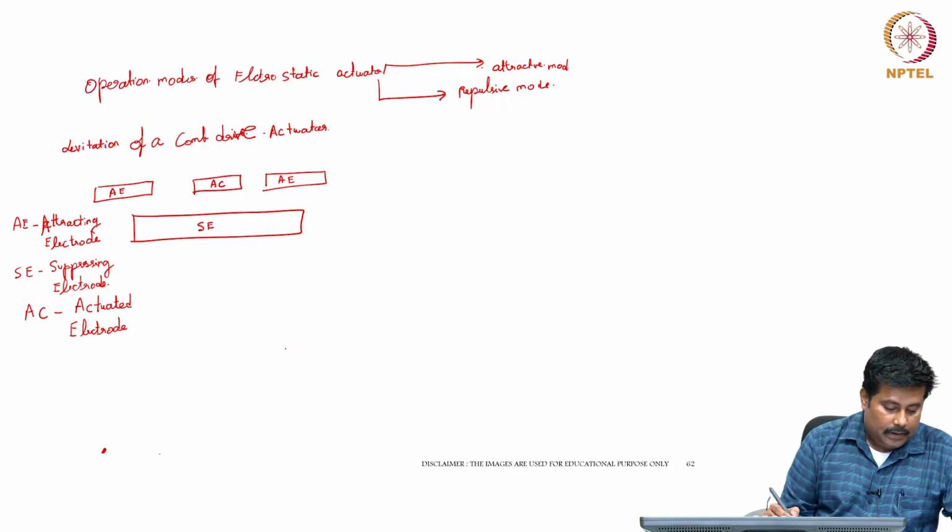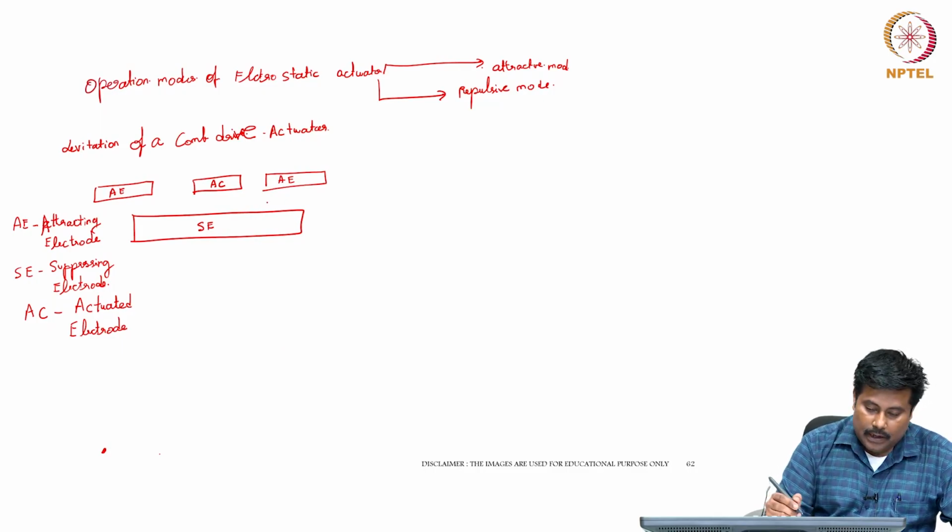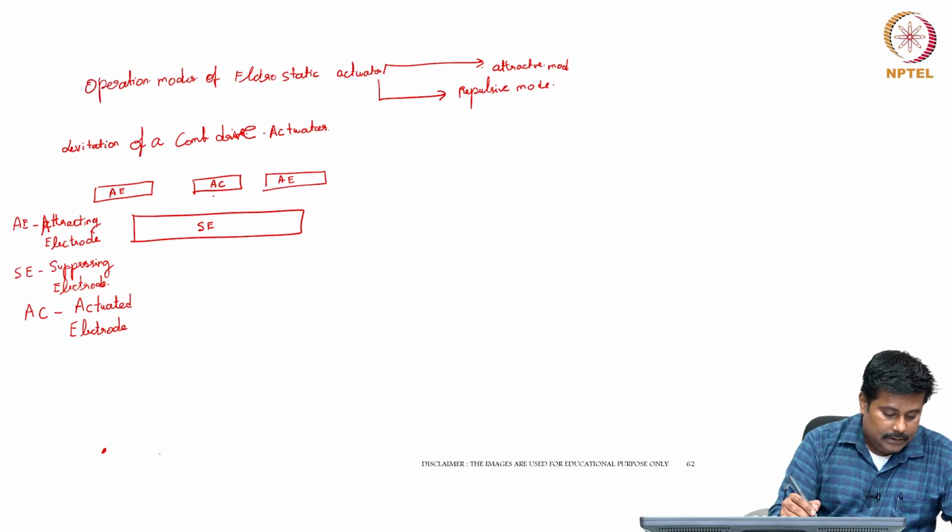So in this particular configuration, if you see, this is a kind of configuration which is used for a comb drive mechanism. There is a suppressing actuator, and the attractive force acting between the charges causes a displacement by decreasing the gap. So here we will be having the forces Fu, Fd, Fr and Fl.